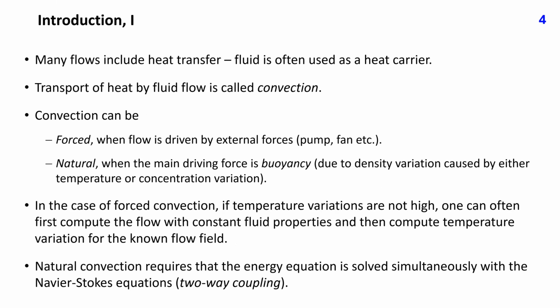Many flows include heat transfer. Fluid is often used as heat carrier. The transport of heat by fluid flow is called convection. Convection can be forced when flow is driven by external forces, for example pump, fan, etc., or natural when the main driving force is buoyancy due to density variation caused by either temperature or concentration variation.